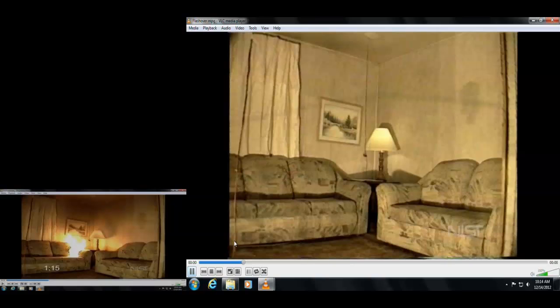And this is still a cold ceiling because this is a relatively thick material. It's this gypsum board, most likely. And so this thing is still relatively cool. And so radiatively, it's cool. The radiation heat transfer from any location in this living room to the upper layer is still probably dominated. It is, in fact, dominated by the cool ceiling temperatures.